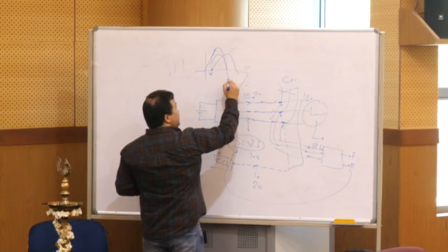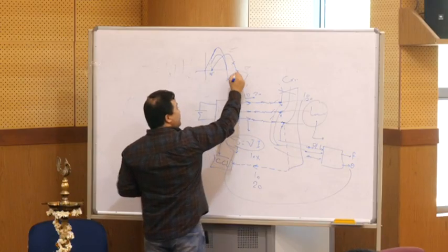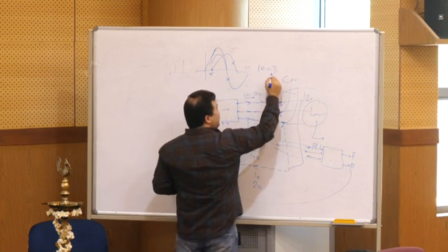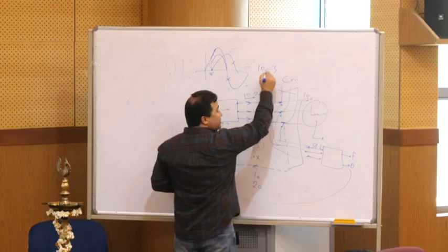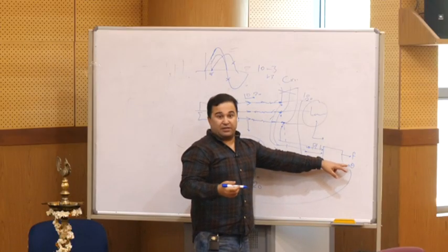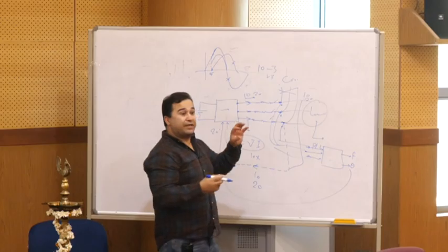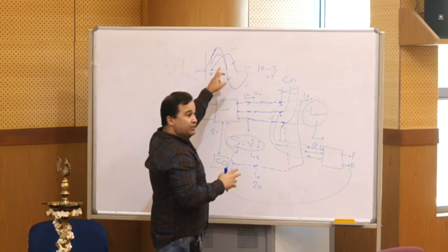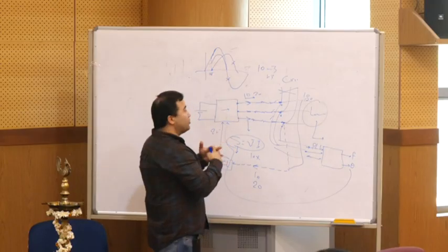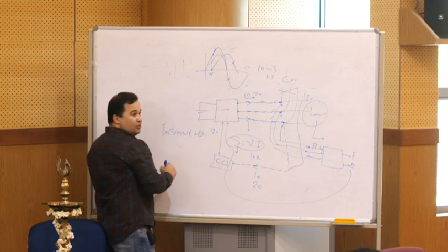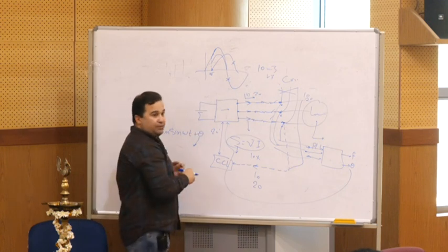Assuming that we start from here to here, what happens here? Here the current is negative, here it is positive. So for example, the grid is -3, and having +3, we have -3, so it makes the problem. So the PLL provides the theta for us, the instantaneous angle of the grid, and says that when you connect to the grid, you should be matched with this, so your starting point is I max sine omega t plus theta. You get this theta from the PLL.